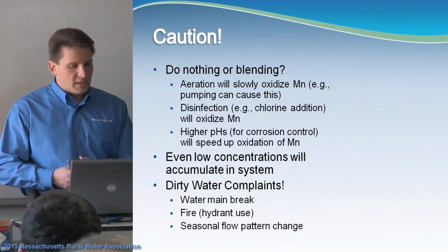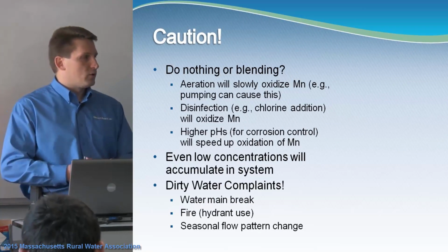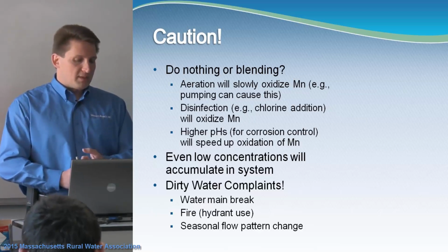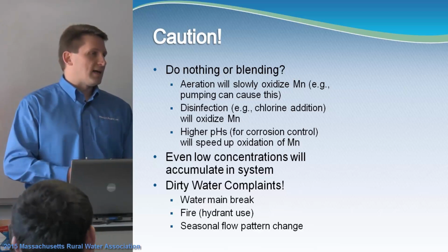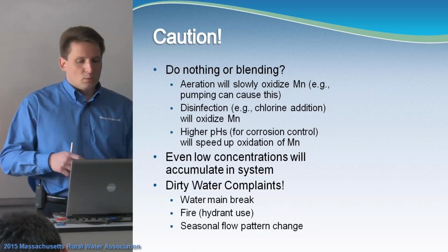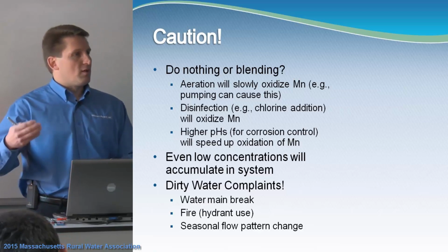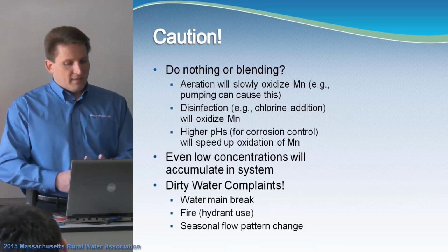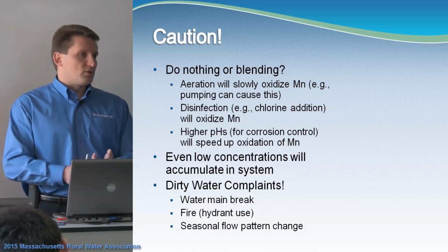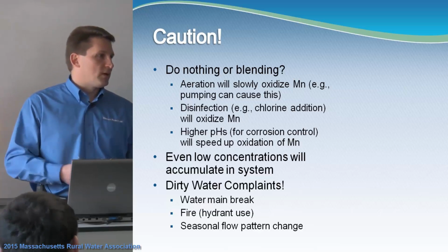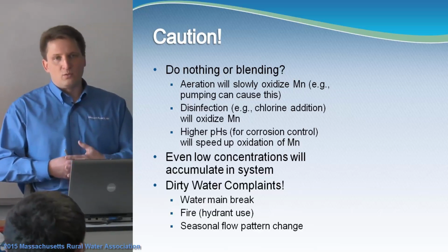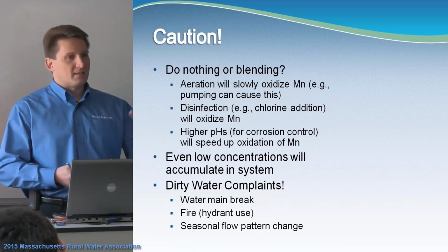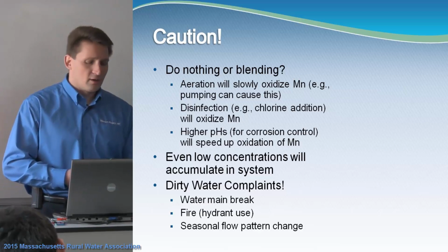A word of caution in regards to some of those do-nothing scenarios or the blending scenarios, because one of the things that you need to know about is aeration in particular will slowly oxidize your iron and your manganese. Sometimes pumping can cause this just through all the turbulence going on in the system and in the wellhead. Disinfection itself, chlorine is an oxidant, whether you're using chlorine gas or hypochlorite, whatever you guys are using, that is an oxidant. And if you chlorinate your water and you have iron and manganese in there, particularly manganese, you will oxidize it, and it's going to turn into that black mess that you guys saw earlier.